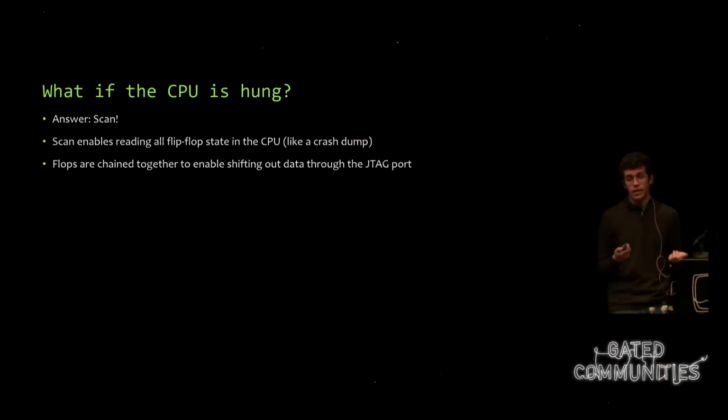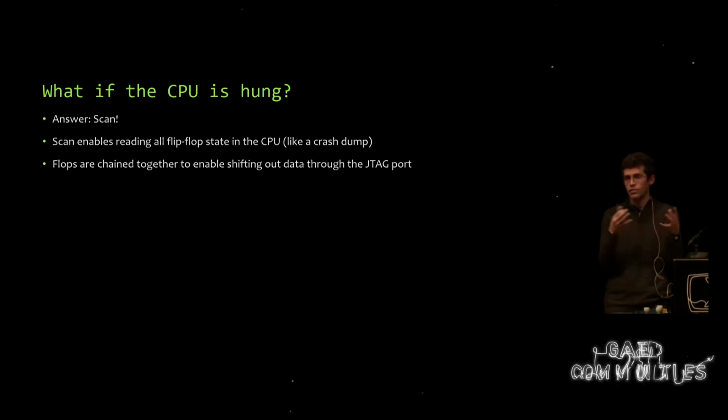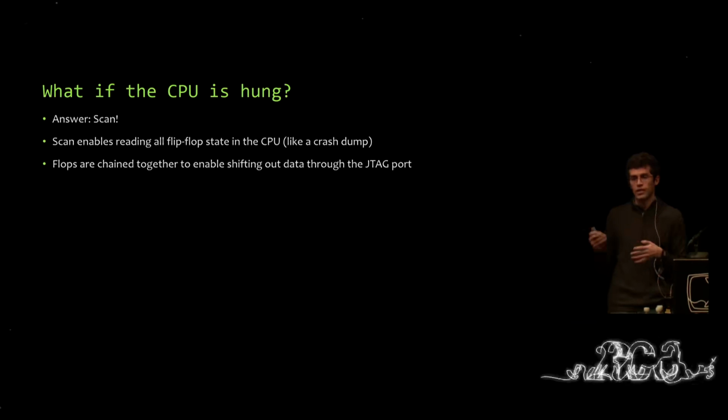This sort of thing can be very useful. It's kind of like your GDB, but it doesn't always work. And in particular, one very common thing to happen with silicon designs is the thing will just hang, and it'll be completely frozen, and there's nothing you can do to it. So how do you debug that? The answer is something called a scan dump. And this is a feature that is kind of like a crash dump. Basically, you take all of the register state, all the flip-flops on the design, you dump them all out through the JTAG port so you can go and analyze it.